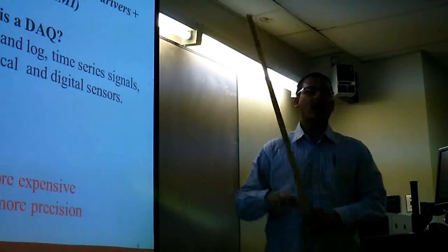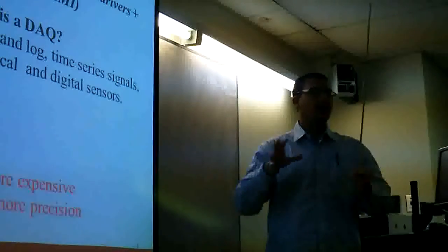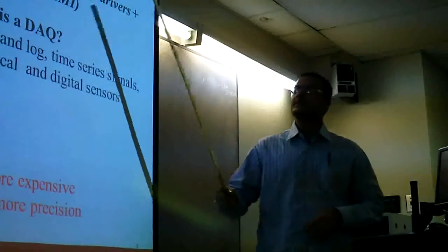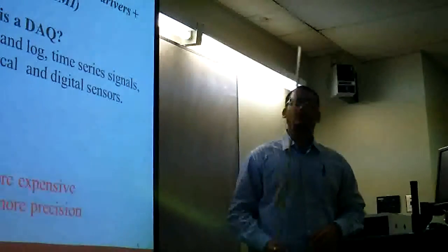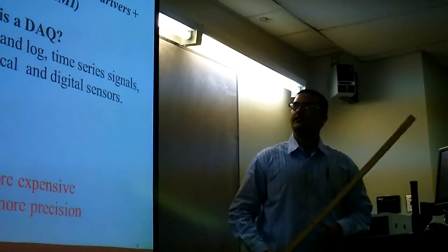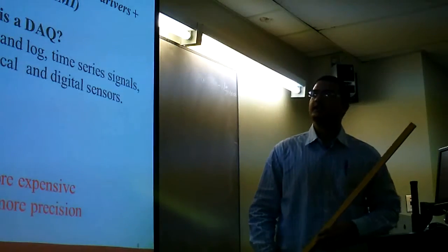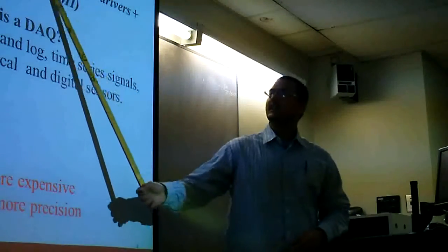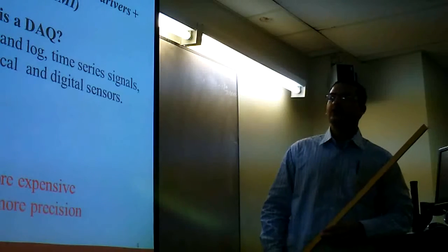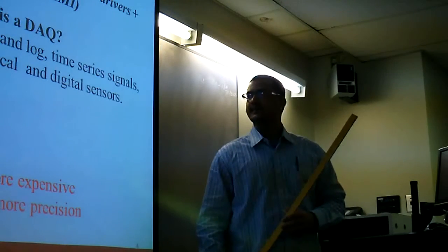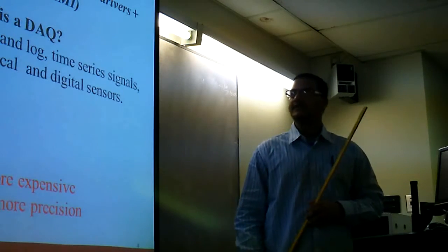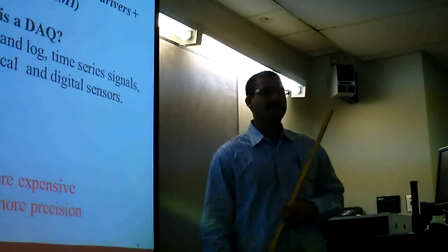It's nothing but a collective group of computer systems, sensors, data acquisition cards with some device drivers, and application software for the human-machine interface. The main component is the data acquisition card, which is an electronic device to sample and log time series signals from various physical, chemical, and digital sensors.